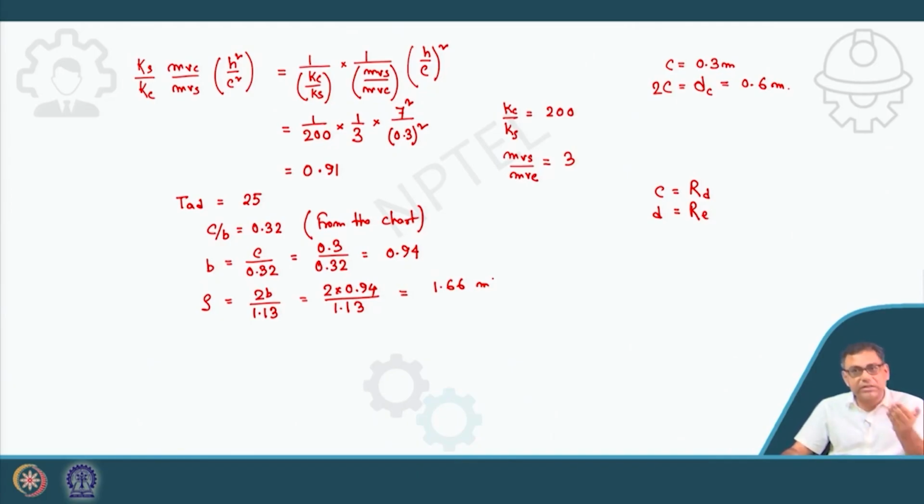If you consider the stiffness, your RU value will reduce, but the permeability effect is more significant compared to the stiffness effect. So that's why the net RU value, if you consider both permeability and stiffness, is governed by permeability, which has the higher effect compared to the stiffness.